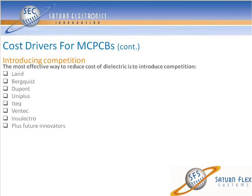So the main thing is that last point, future innovators. I'm a bare board manufacturer. People come to see me to sell material. I swear I've not had more visits than in the last 3 months from people pushing new product. And it could be very well fantastic stuff. It could just be an equivalent. It doesn't matter. The main thing is there's people entering the market. By speccing out a brand name, you're not allowing yourself to take advantage of that. Also, you're not securing your supply chain. If you find that they're equivalent material manufacturers, allow the use of all of them. That way, if someone wants to quote a 12-week lead time, someone else might come in at 3. You're really just ensuring your supply chain.